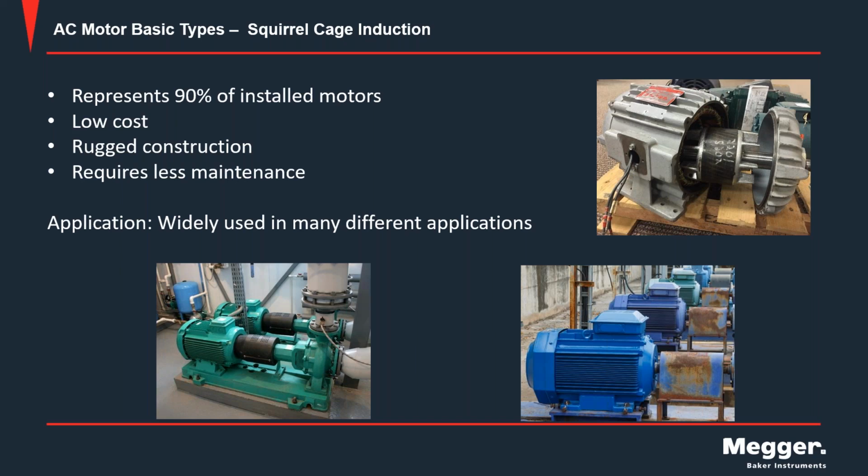And so the rotor there has no windings on it. Its construction is of a core center with copper bars or cast aluminum bars poured into a casting there to form the bars. So there's actually no windings that we can test there. So primarily what we're going to be looking at with static testing is only the stator insulation. So insulation between the turns that's on the wire itself and the insulation that's laid into the ground wall or the slot of the motor is actually what we're going after here.